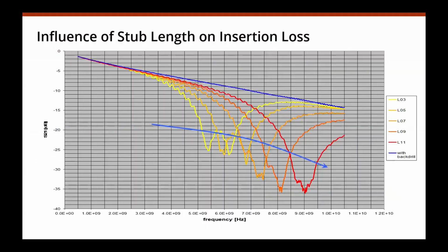And then this happened. I had a design where we had traces on different layers, and the ones that had been very close to the top surface, the yellow one, layer 3, had a very big increase in losses, even already at say 5 gigahertz, while traces on other layers that were deeper down in the stack, like the red one, had not so much impact. And what we really found at that point of time is that the longer the via stub, the lower in frequency you get that notch in the insertion loss profile.